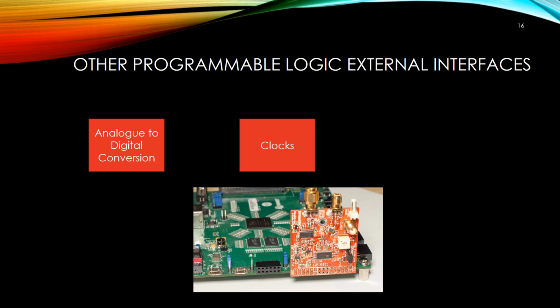The clock. The PL receives 4 separate clock inputs from the PS, and additionally has the facility to generate and distribute its own clock signals independently of the PS. The independent PL resources are equivalent to those of a 7 series FPGA.